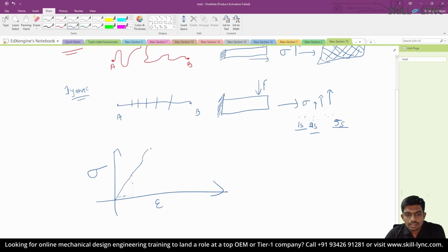And when it enters a nonlinear region, as the displacement increases, the stress value doesn't increase that much. Hence, in the static analysis, our solver followed this extrapolated path such that for any value of load that we give, it received the corresponding stress and strain by just extrapolating this curve.